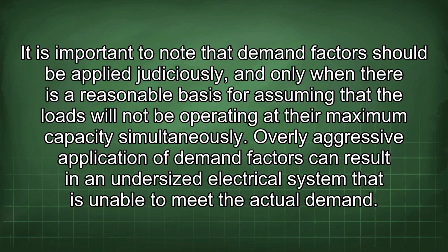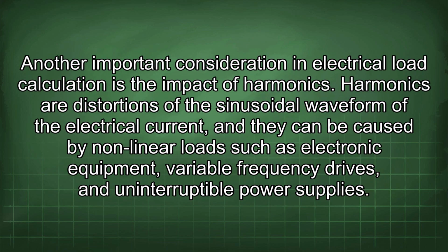It is important to note that demand factors should be applied judiciously and only when there is a reasonable basis for assuming that the loads will not be operating at their maximum capacity simultaneously. Overly aggressive application of demand factors can result in an undersized electrical system that is unable to meet the actual demand.